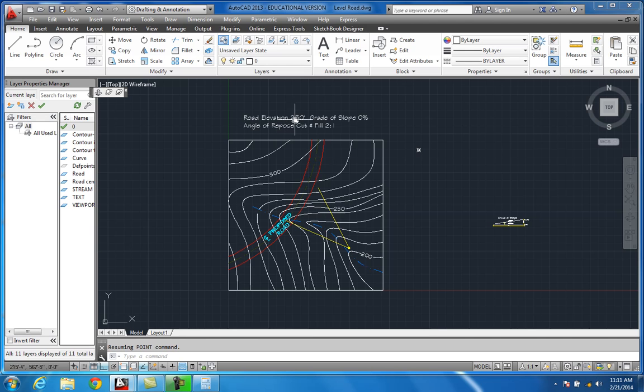My elevation, I got that at 250 foot. So this road's at 250 foot. Now, look in here, and these are contour lines. And this shows you on the horizontal plane what the elevation of this terrain is. You got 200 foot, 250 foot, up to 300 foot. Now, we got to know the contour interval as well.